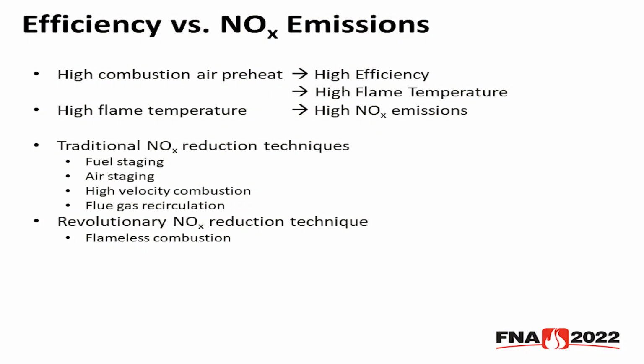So there are a number of techniques, many of them around for several decades, to help combat this. Some are fuel and air staging. That's really the same idea, but you're just playing with a different leg of the fire triangle, fuel versus air. So in the case of air staging, which we use in many of our burners, you bring in a portion of the air, mix it with all of the fuel, generate a partial reaction, which is substoichiometric at that point, and release some heat.